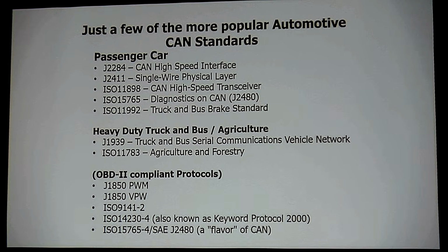So in this particular system, now we are going to give some CAN standards. So the CAN standards, this is why CAN's used. We all want to know, why did they pick CAN? There's lots of different really good communication networking schemes that work and give you high parametric data. The difference is CAN only sets a standard. That means it says you sort of build it like this, and this is sort of how we want you to build it, and then the manufacturer can take it and put their own flavor on it. There's no CAN that says, this is the way that this is done.